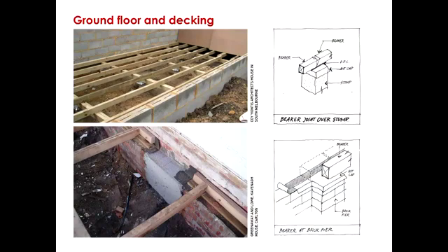A decking system, this is the sort of detail in which you have the stumps, the hand cap, to make sure that termites and other elements won't be able to climb. The bearers and the joists running in the orthogonal direction are supposed to be treated to make sure that termites don't eat the timber and create tunnels. That is the sort of connection that you could do should you need to extend the length of a bearer member or of the joist member.